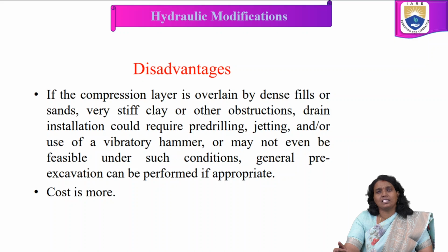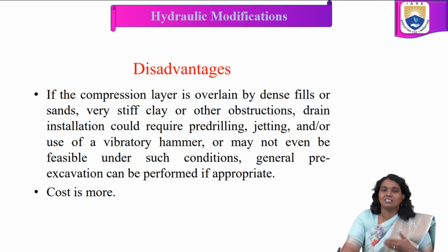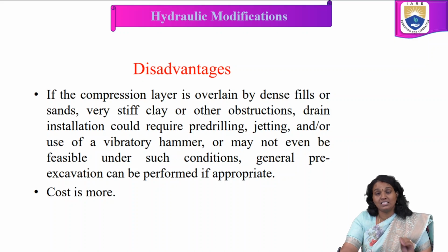Coming to the disadvantages, if the compressible layer is overlain by dense fills or sands, very stiff clay or other obstructions, drain installation could require pre-drilling. So it depends upon where we are going to install these PVDs. Such disturbances may obstruct the installation procedure. For that, before installation we have to do pre-drilling, jetting, or use a vibratory hammer. It may or may not even be feasible under such conditions.